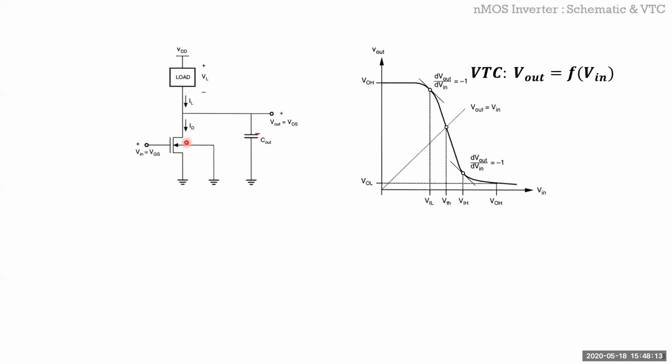Like I said, when it is on, your output voltage is some output voltage VOL. It won't be exactly zero because now you have this thing fighting it all the time, so there is always a residual current through this. When this is off, it is almost charged to, or in this case, the way it's shown here, charged to VDD. And that's what's called your output voltage high, VOH. This is called your voltage low. And in between, there is this transition period. It's not exactly the ideal one I showed before. And we'll go a lot more into detail on what goes on in this transition period.